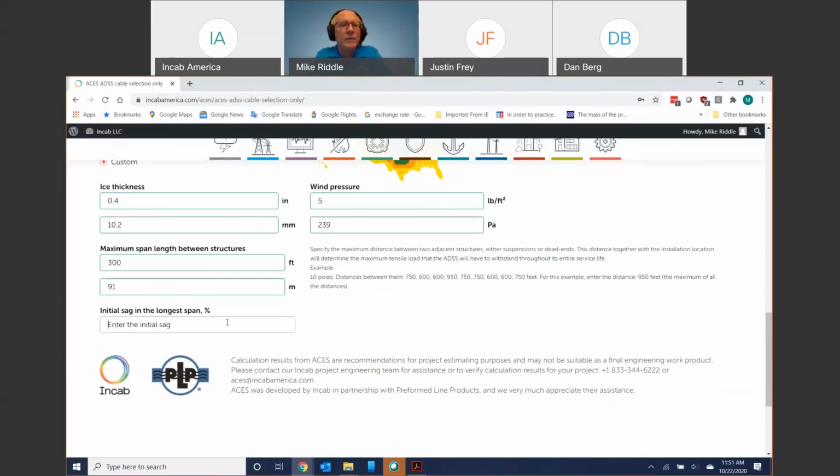Metal cables are generally more in the range of about 2%. So already you're kind of tight there with ADSS. You do kind of like the tightness in one sense because ADSS is very stretchy, and so by installing it tight, you do some mitigation of sag under wind and ice loading. But going below 1%, I think you've already got kind of a banjo string up there. I wouldn't do it, but some people are doing it. So today, let's stick with 1%.